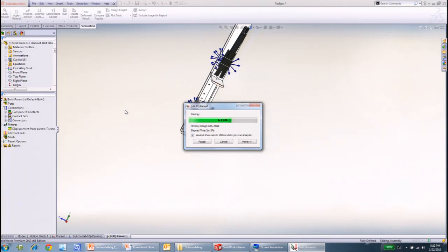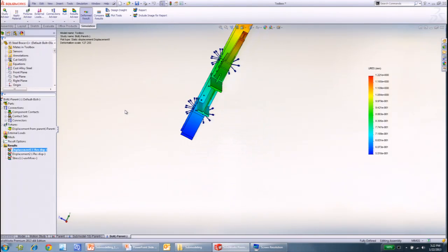So when you do submodeling, you don't have to redefine your load. No, your load is still the same. Because if you redefine the loads of the submodel, you're changing the physics, which means that effect is not taken into account in the parent. So we said we are going to allow you to add it here. We can only add contacts and connectors, assuming that you'll use it wisely.